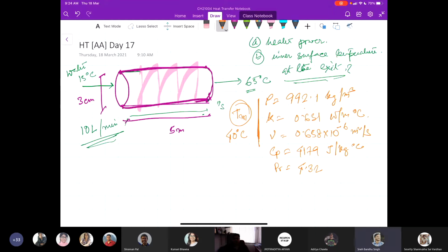By the heat capacity of the liquid and the flow rate. Right. So you have a known flow rate and you know how much the temperature has to increase, which means how much heat we have to provide. That is m dot Cp delta T, if it is mass flow rate. Yes, sir. That is your heater power, in fact. That much energy you have to constantly supply.